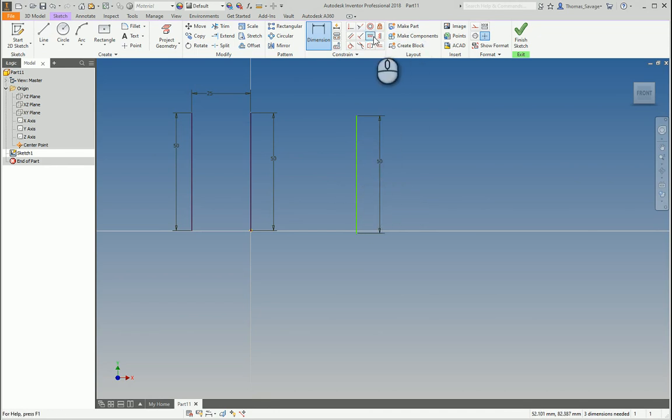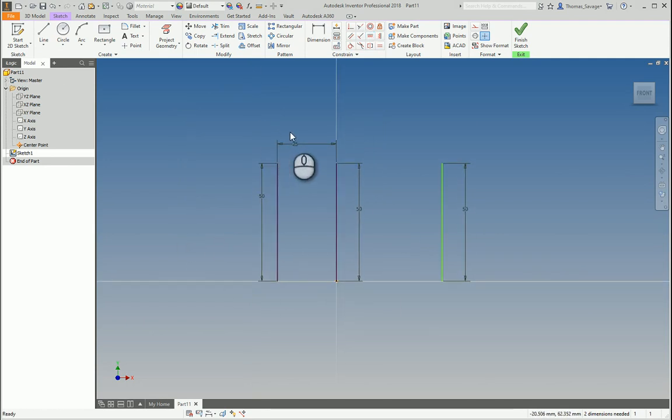a line, another way to use the horizontal actually, which I'm going to use now to show you while we're doing it, is if I select the bottom point of this line and then the bottom point of this line, it puts those points horizontally, which is very handy. So now we have 25 here and 45 there. The symmetrical will allow us to select these two, select the middle, and then that will make this distance 25. Pretty simple, comes in handy.